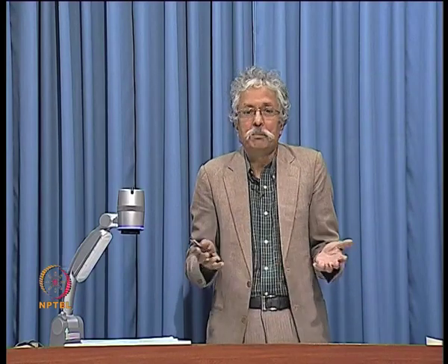So, what I would like you to do is take psi around 45 degrees and try to find out what kind of values of alpha you will get. Is it tenths of degrees or a fraction of a degree, or what numbers are these? And why don't you try to find out the value of psi at which alpha will be maximum. There must be some propagation direction K vector where I will get maximum difference between the S vector and K vector. That means maximum difference between the propagation direction of the wave front and the energy.